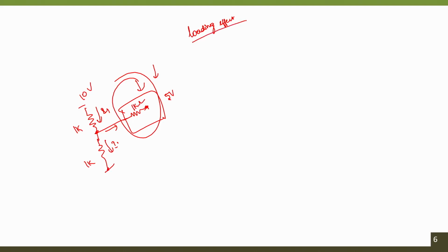So, when we are designing a circuit, make sure that it is not loading your input. When it happens, you are losing the information. So, that is the major characteristic of any subsystem when we are interfacing between two different subsystems. These always have to be remembered. So, we have already understood that the input impedance of the system should always be high.